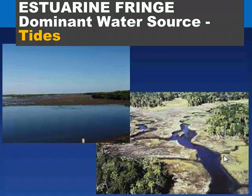Estuary and fringe wetlands, these are wetlands that are simply dominated by the action of ocean tide. That might be the actual tidal fringe itself, or it might be as far up in an outlet stream that we're getting tidal influence. But tides are obviously very cyclic, twice daily. And one thing to point out with estuary and fringe wetlands is water typically moves in and out of these wetlands in discrete tidal inlet channels. Water rarely moves in and out as sheet flow.